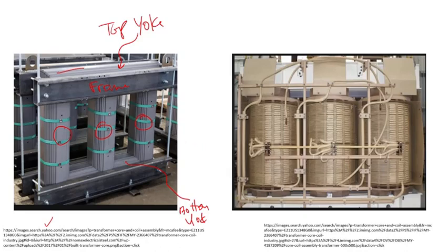Then what they would do is stick a strap inside between the laminations, from aluminum, for instance. Then they would bring that to, for large transformers, typically a bushing. So a core bushing, then they will ground that bushing externally.